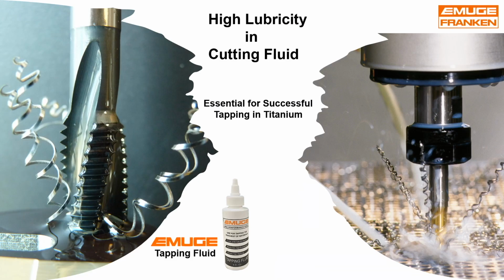Successful tapping in titanium requires very high lubricity from the lubrication method due to the high compressive forces produced by titanium. Machining coolants are categorized into four primary types: synthetic fluids, semi-synthetic fluids, soluble oils, and straight oils. When using synthetic fluids, the concentration of oil content is a critical factor for the level of lubricity provided in the tapping operation. Higher concentration levels are essential for successfully tapping titanium. A tapping oil specially formulated for difficult materials such as EMUGE tapping fluid provides the highest level of lubricity.